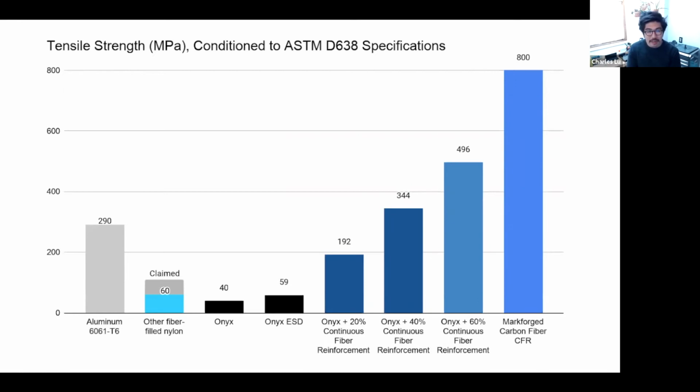And that's because they were purpose-built designs optimized such that you could route continuous fiber all along. What that requires is a little bit of ingenuity. It's sort of like designing for a casting, in that you want uniform cross sections throughout, but you would change the cross sectional width and section thickness such that you could fit more fibers through. We do have a design guide and a lot of content online about how to make this design for additive manufacturing work.